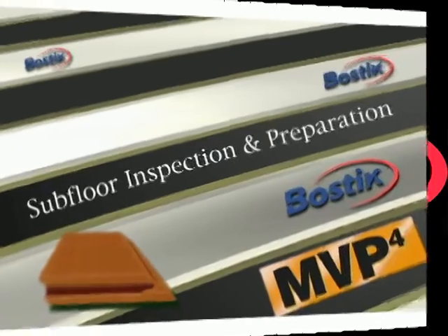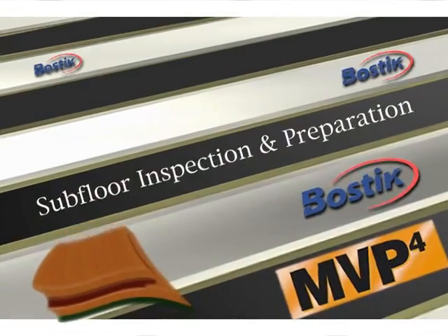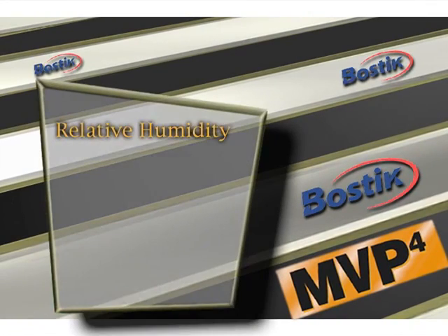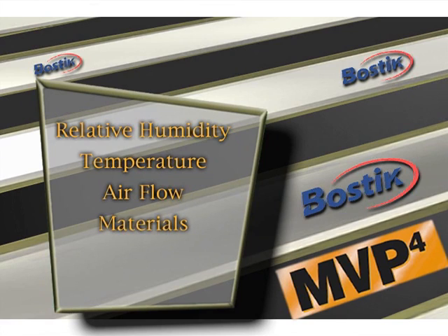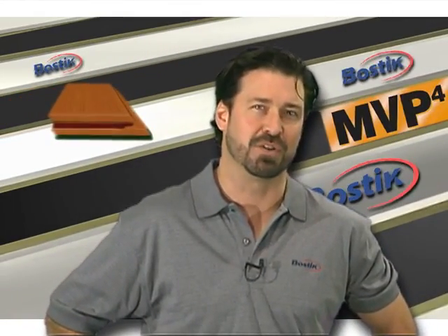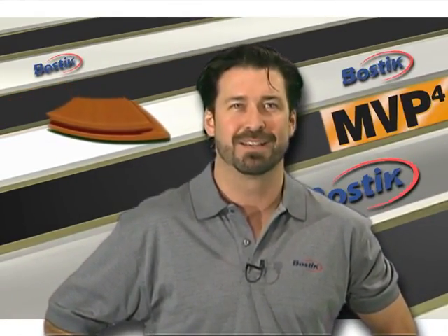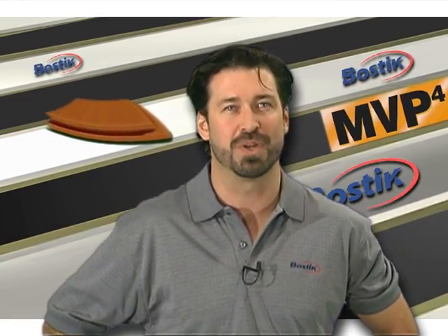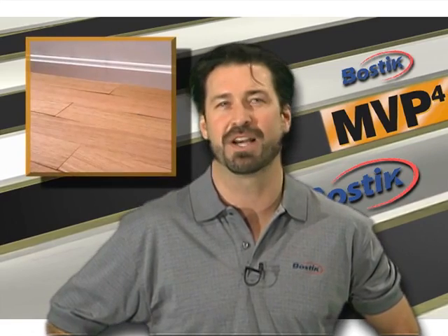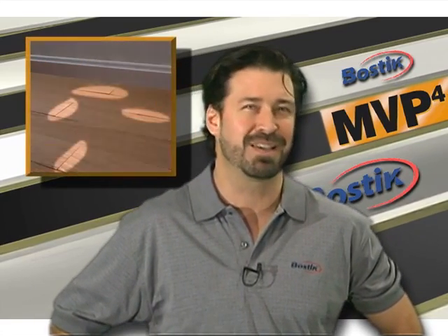The moisture levels in wood have a tendency to fluctuate. Wood flooring moisture levels are affected by many surrounding job site conditions, such as relative humidity, temperature, airflow, construction materials, sidewalls, and concrete subfloors, to name just a few. An increase or decrease of the moisture levels within your wood flooring can result in dimensional changes to its original factory milled shape. These dimensional changes may lead to unsightly flooring issues, such as cupping, gapping, end lifting, and warping.